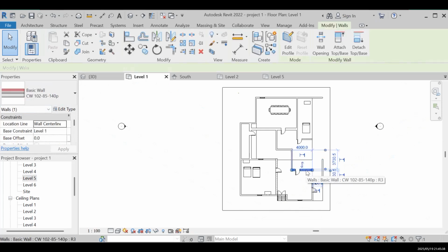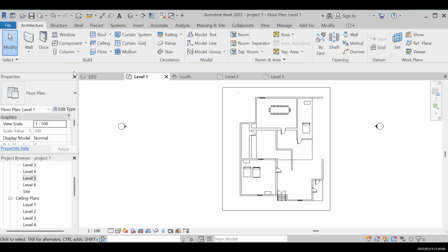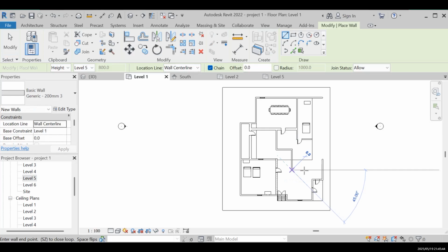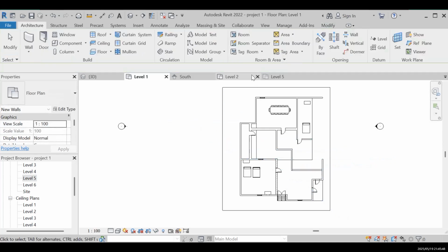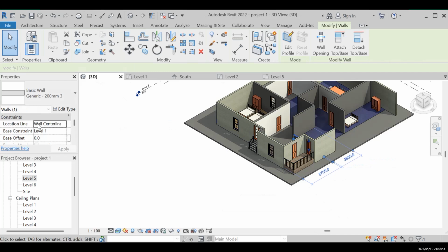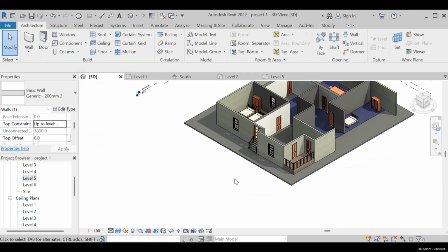So I'm gonna just delete this wall, and I can just go again here, and then here to here, simple, right? And then, all right, I forgot to change the level, so it should be from the level 1 to level 2. Okay, and then apply. All right, so we have our first balcony. So it's not over yet.